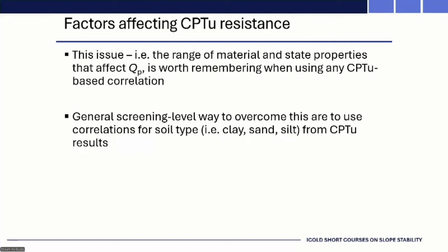It's not a bad idea to pick a few points from your CPT probe, take the tip resistance, the friction ratio, the pore pressure, and go and plot where that sits on some of these charts. Just do it by hand and see, is it actually consistent with what the software is spitting out? Because then you might have a better idea of where the phreatic surface is, so you can actually normalize maybe in a better fashion, etc., etc.